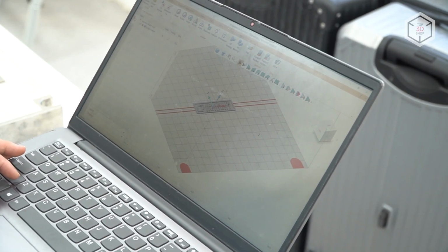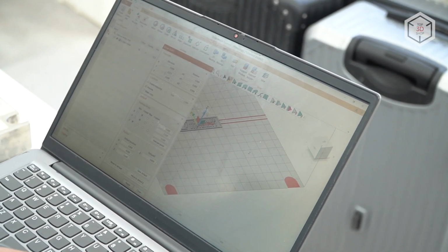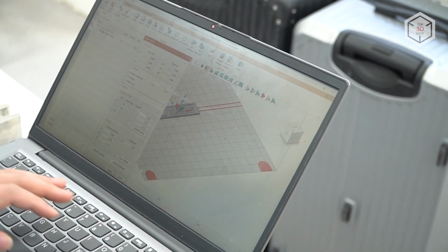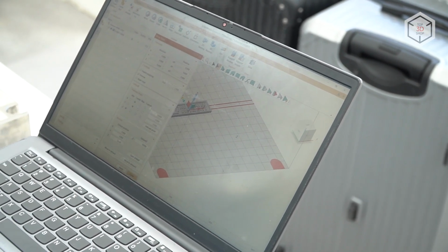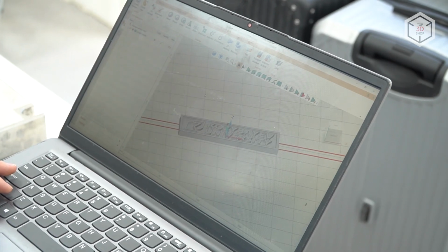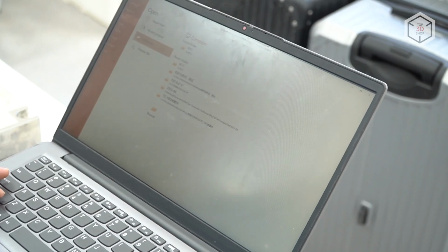Today we'll be printing the logo of the university which we modeled. And here's the Voxeldance Additive software, which we use in order to add supports and make sure that the model is positioned accurately. And after Voxeldance Additive, we'll move to HBD Build Expert, where we're actually setting the path for the laser.